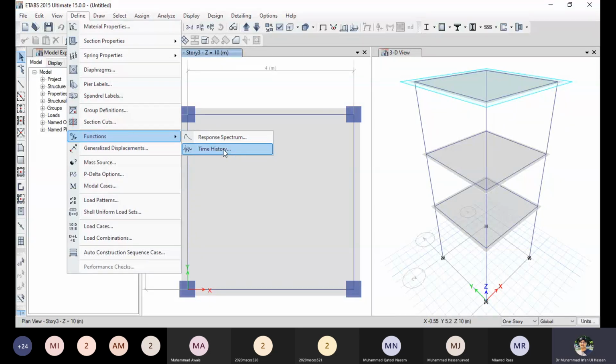So there are many types of analysis, but the advantage of time history analysis is that you try to simulate the real loading, earthquake loading, or any other loading which varies with time, on the structure, and you see the response of the structure not at the maximum response only. You can see the response of the structure at different time steps. If you are giving 20 time steps, you can see it at all the seconds. If you want to see the response at half of a second, it's up to you what delta t value you give in the time history. And you can see the peak also, when the peak response occurs, what vibration was applied to the building, and at what instant the peak response occurs. You can see that by the time history analysis.